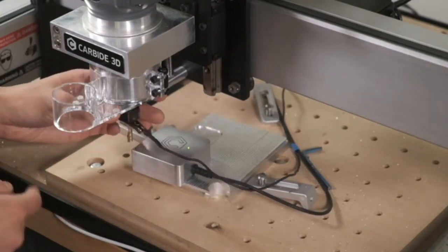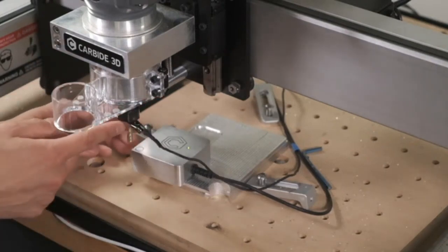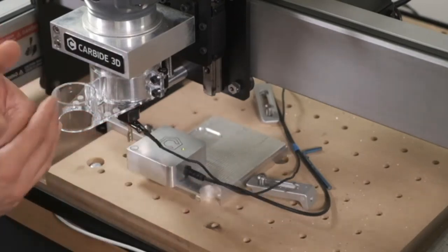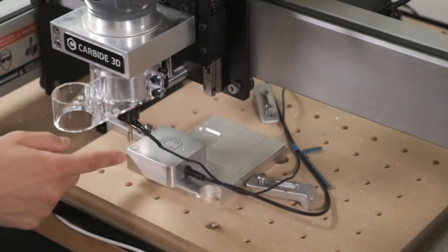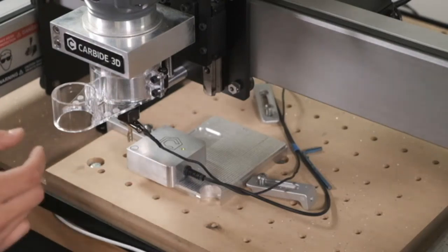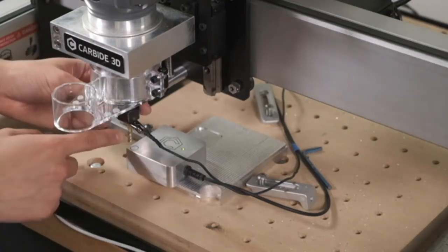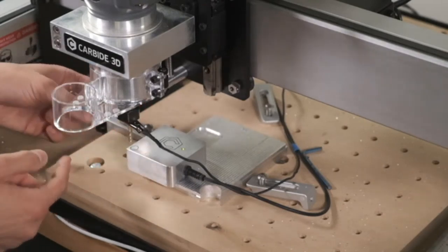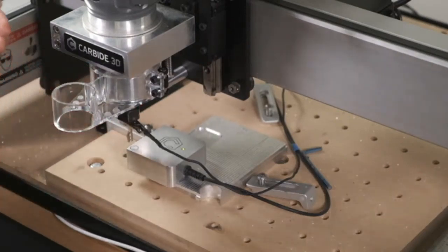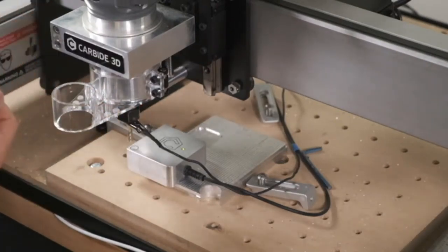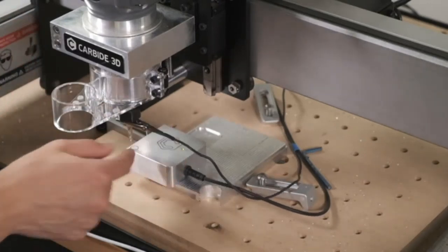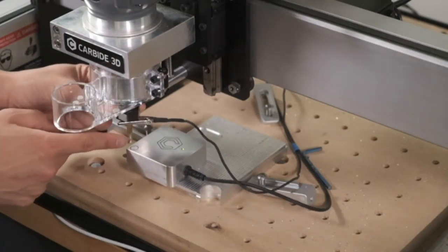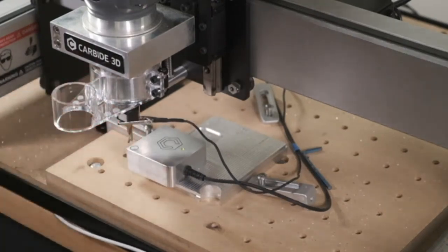So for maximum accuracy, you could take a 1/4-inch dowel pin or something and stick it in here. And that way, when the side of that dowel pin hits the touch probe, you know for a fact that it is 0.125 inches from that wall. A single flute end mill, or even a 2 flute end mill, will sometimes not give you a perfect reading because you might fall in one of the valleys of the flutes contacting the walls or the outer edge of the flute. So if you're picking up the edges, just make sure you point one of the cutting edges or the point of the end mill towards the bit zero.